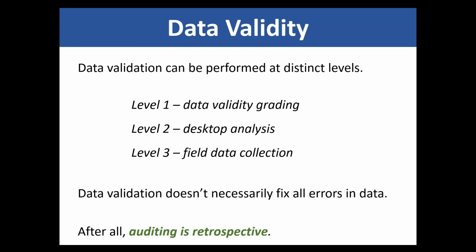You can dig a little deeper into a level 2 validation, where you really interrogate your databases and your raw data sources for that data story making sense and dig into the systems that produce your numbers. And then you can go to a level 3 if you are so inclined and work with field data collection and test your meters and do pilot leak detection to confirm the results of your audit, and go out and pull customer meters and put them on a test bench and do some pressure logging.